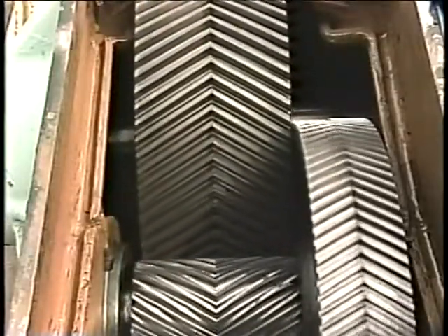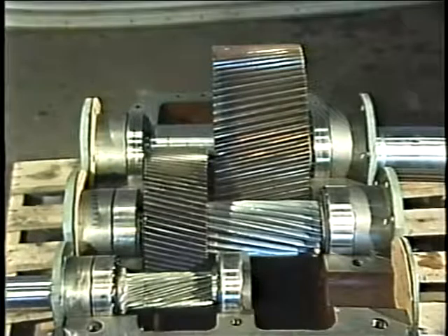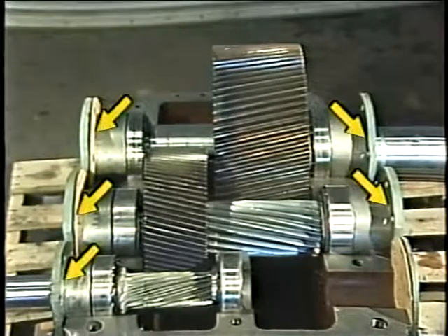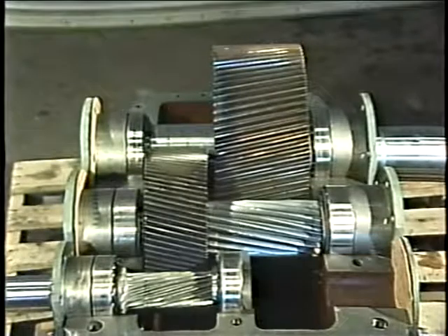However, too much end play could prevent the proper meshing of a gear and pinion. This could cause uneven wear problems, overheating, alignment problems, and in severe cases of axial movement, could even cause the teeth to break. End play can usually be adjusted by installing or removing shims from between the end caps and the bearing housings. This places the gear and shaft in the proper position inside the casing and controls the amount of end play by limiting axial movement. The manufacturer of a gear set will normally specify the allowable amount of end play associated with the gear set.